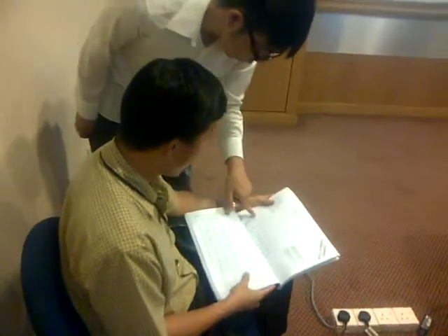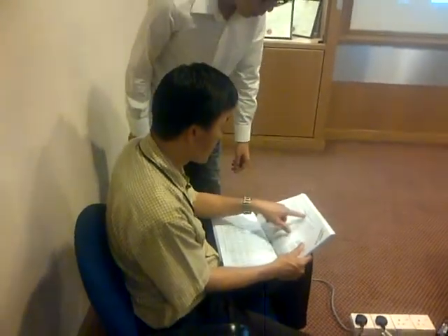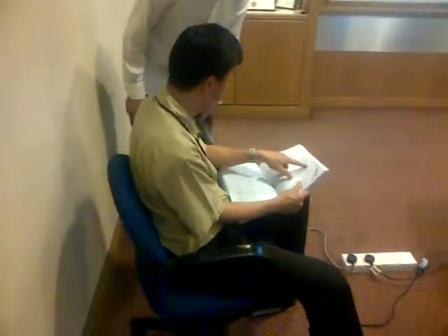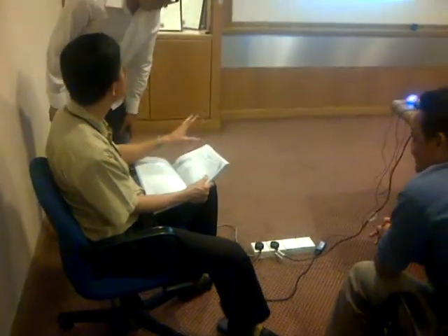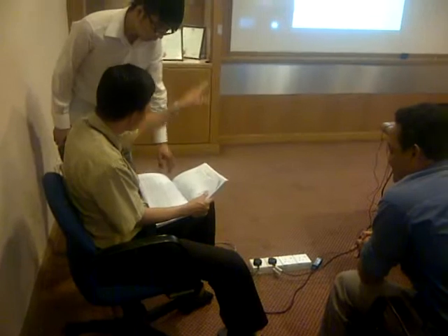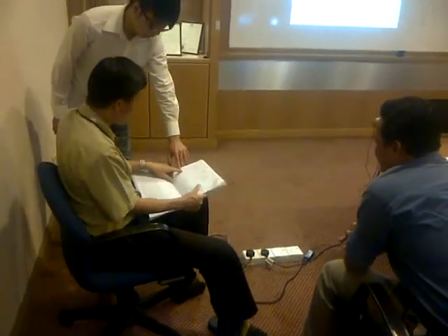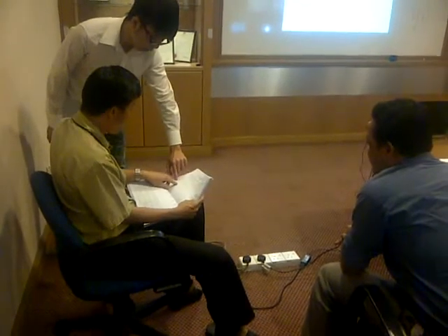Okay. Which cable? So you are single core, correct? You are using PVC insulated, correct? Non-armored, correct? You must know how to differentiate armored and non-armored, different cable also. There are many different cables here. So this is correct, means your cable, you are sizing based on it, you refer to this data.